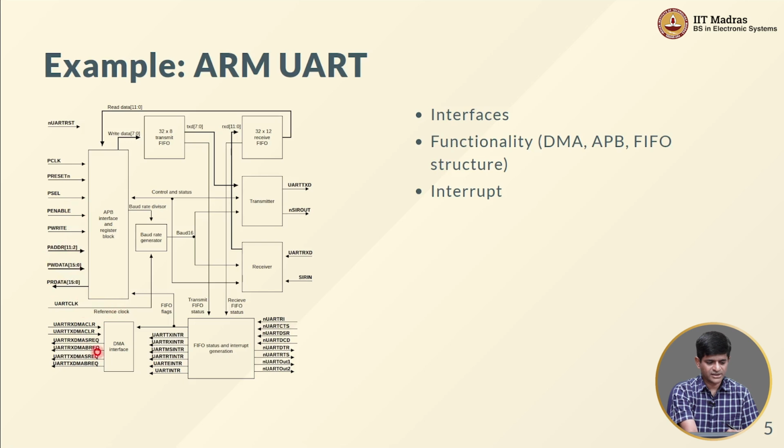There are a bunch of other things that you can see over here which are related to what is called the direct memory access or the DMA interface. Now, as you can imagine, DMA is primarily used in scenarios where you want high throughput, a large number of bytes in a relatively short amount of time. So, programming it is not trivial, but on the other hand it is well known. There is a systematic approach to do it, but you need various kinds of things such as the DMA request, the address requests, and so on, and all of those are essentially provided by the DMA interface.